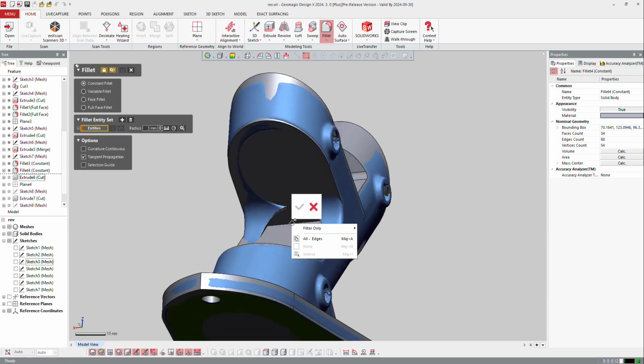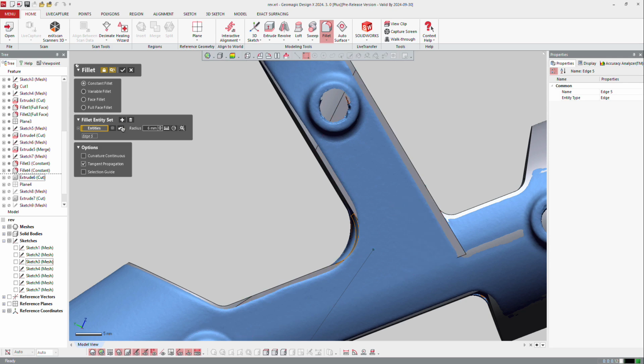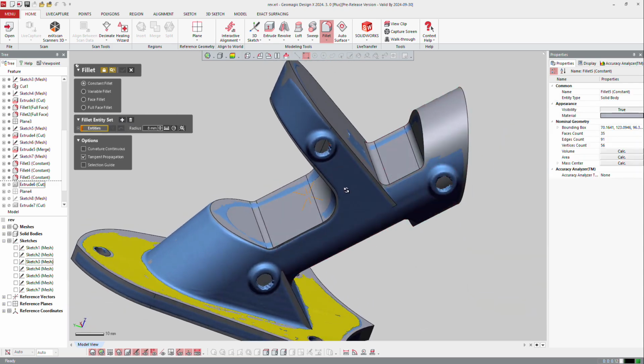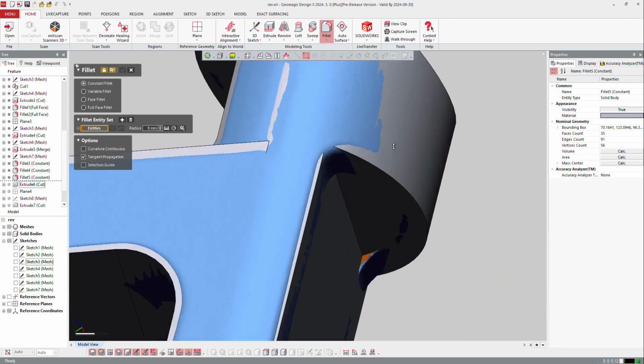If I want to make that one here, it can be the same. So I can select that, look at the fillet, and again, make it bigger, 6 or 7 or 8. So you can increase here the fillet and check 8 millimeters. Okay. And now I got all my main fillet done.